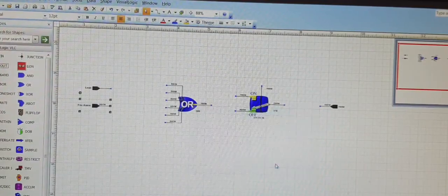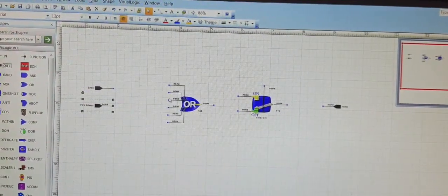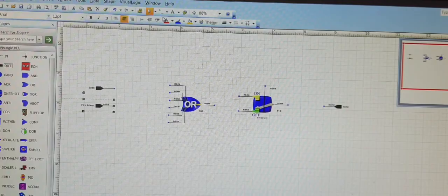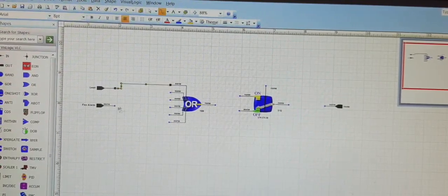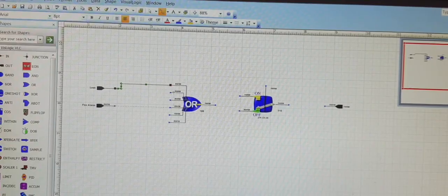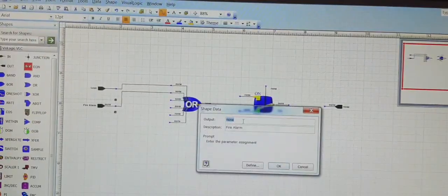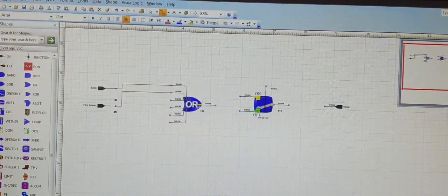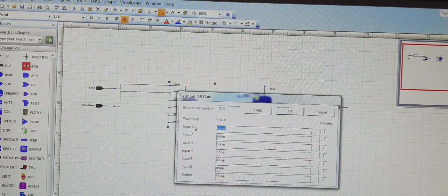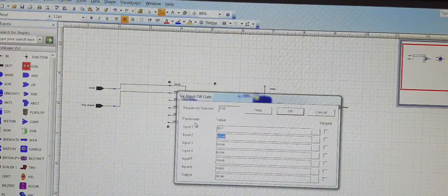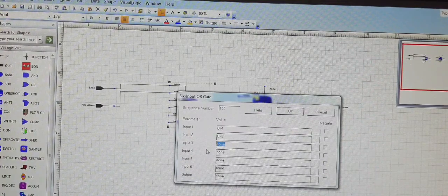So let's make sure there is no water leak detected and there's no fire in the system. Let's say we don't have any leak. Let's consider binary input 1 is leak, binary input 2 is the fire. The rest of them which you're not using, always remember to keep them as 0 or false.